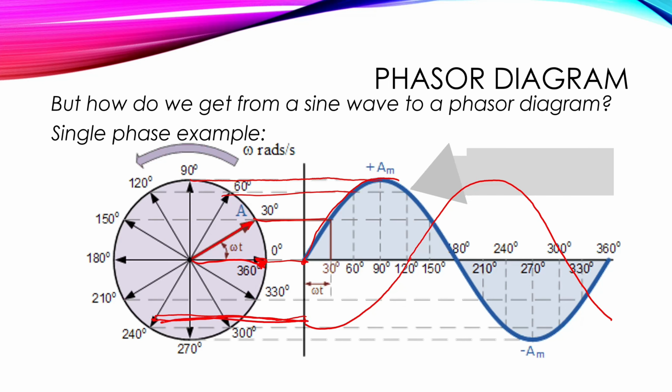And where is C phase? Well, C phase, if we were to plot this on here, right? C phase is going to start at the next 120-degree increment, right? And it's going to go up like this. And then we can draw it back down like this, and we can come up to about right here. And if you look, that C phase will line directly right up with 120.